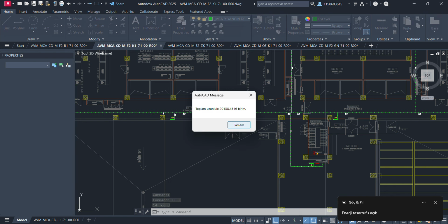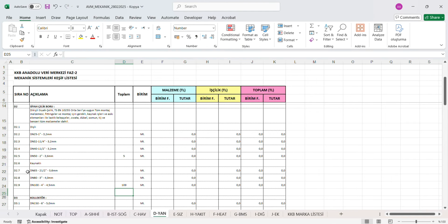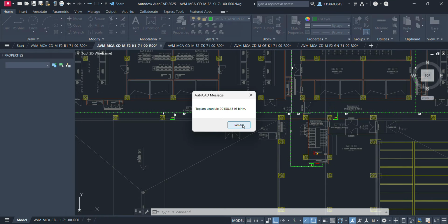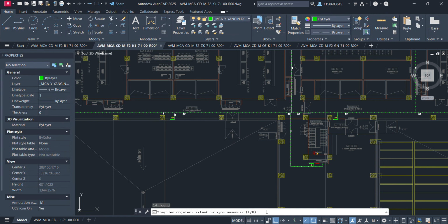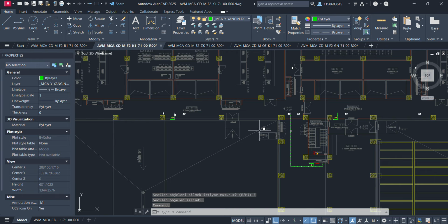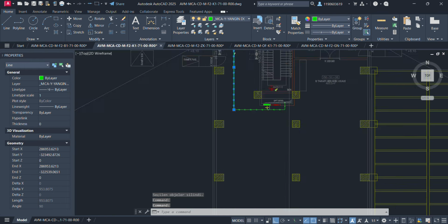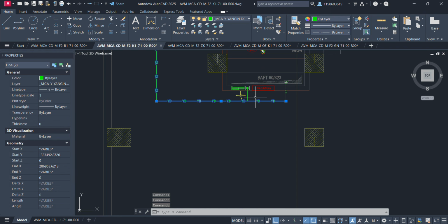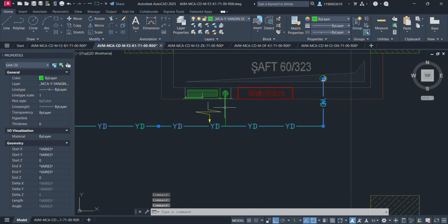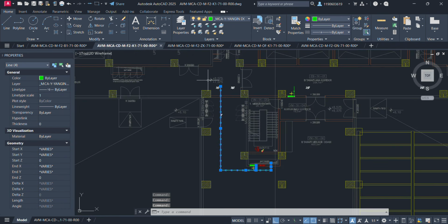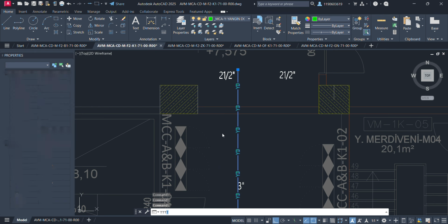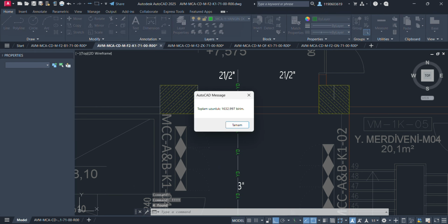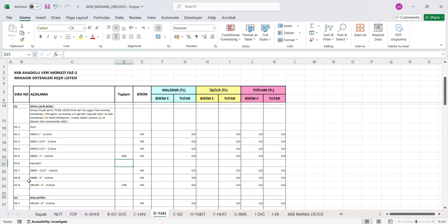Fire systems include many components, such as sprinkler systems, carbon dioxide fire suppression systems, and fire alarm systems. A key factor in designing fire systems is the selection of appropriate pipes and equipment, as the pipes must be able to withstand high temperatures and pressures. In this context, pipes and connectors are chosen based on the size of the area and the flammable materials within it. One of the critical aspects in designing fire systems is ensuring complete coverage of all spaces and areas in the building to ensure that water or gas reaches all potential fire-prone areas. The systems must also be subject to regular maintenance and checks to ensure their functionality at all times.